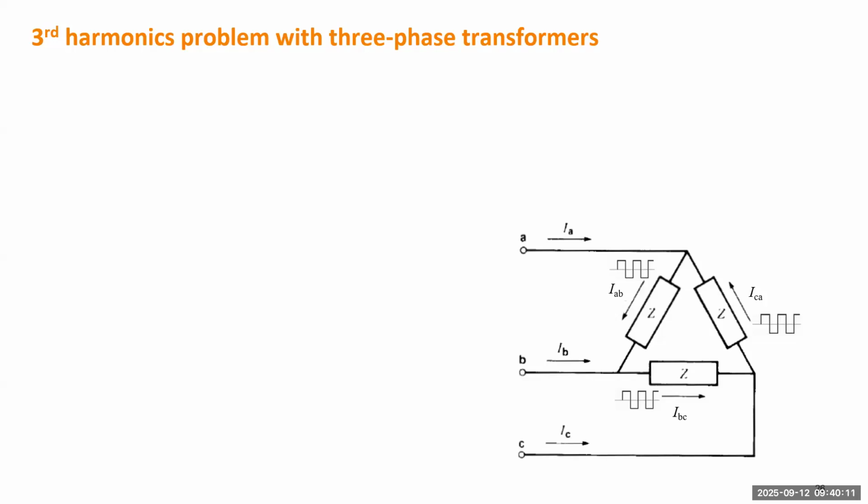It's not very smooth, but definitely you can do the Fourier transform. If you do the Fourier transform, how many harmonics do we have for the square wave? Do we know? If it's a rectangular or square wave, each half cycle is basically symmetric. Perfectly symmetric. So if we do the Fourier transform, definitely you have the omega, that's the fundamental frequency, right? And the next ones will be third, fifth, seventh, ninth, and you can continue. But you only have odd-order harmonics. You don't have even harmonics.